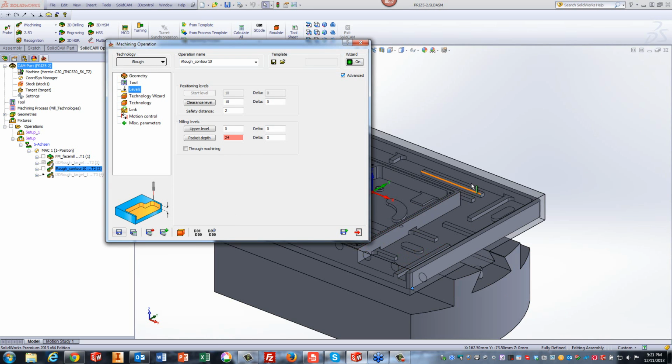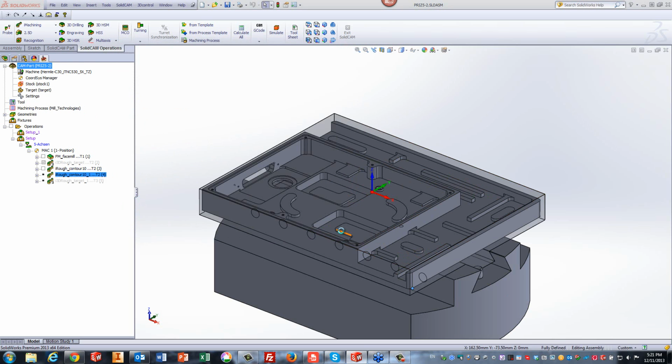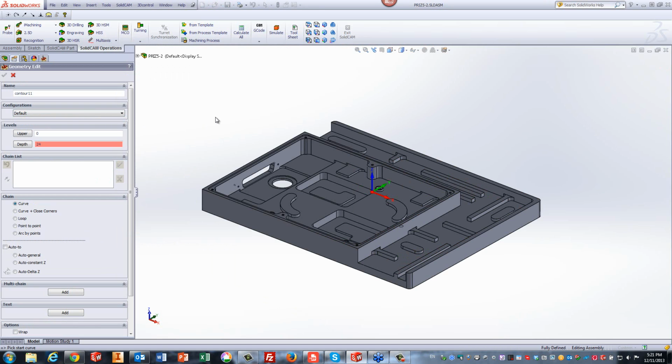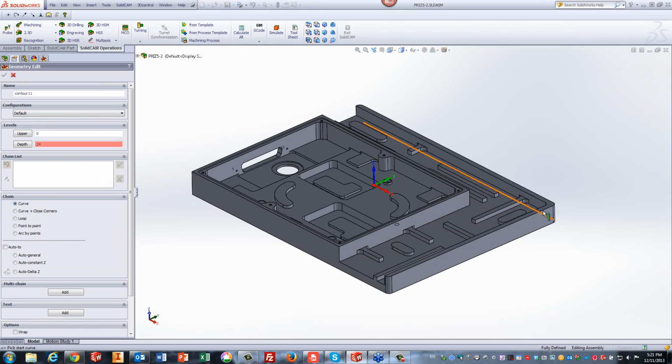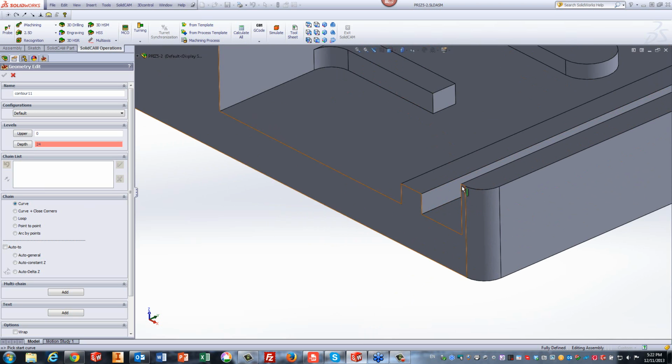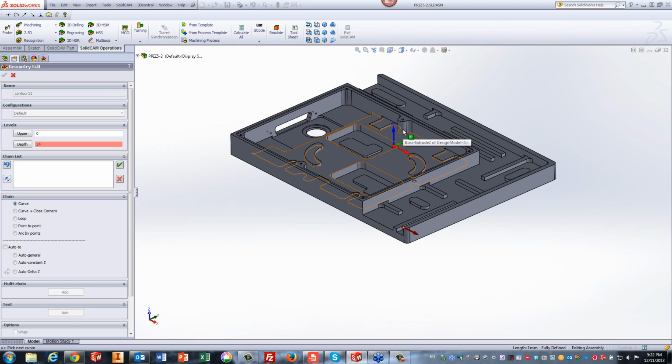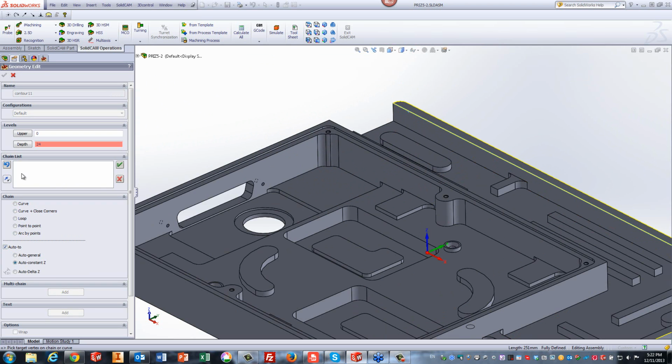Now, my next operation is I would like to actually do this. Let me do save and copy over here. Go to creating a new geometry. And actually, let me take away the stock and let's just look at the default part itself. What I'd like to do now is mill this area over here from this step down here up until here. So my geometry has to be picked around over here up until this point over here, and then going along this closed edge over there. So I'll create it by doing the following. I'll go from this line over here. Let me zoom in so I can really grab it well. And note, I have to create all these geometries. Now this can be time consuming. As you see, that's exactly what it is. And I'll go now, auto 2, constant Z, up until which area? Sorry, I overshot myself over there. Let's do undo.